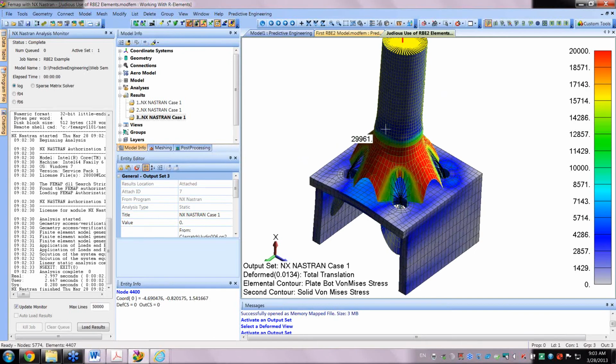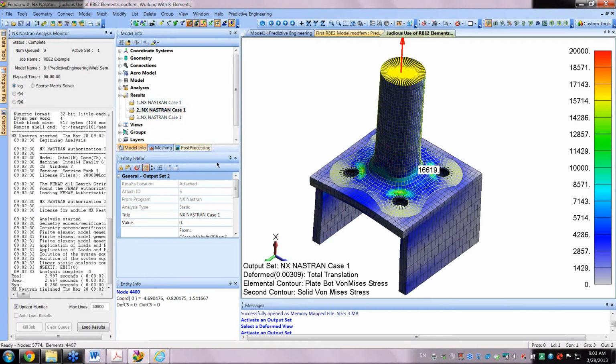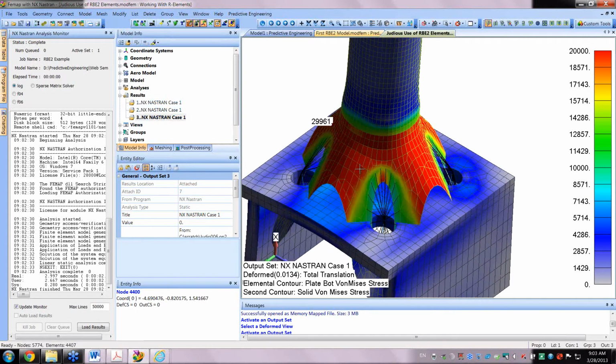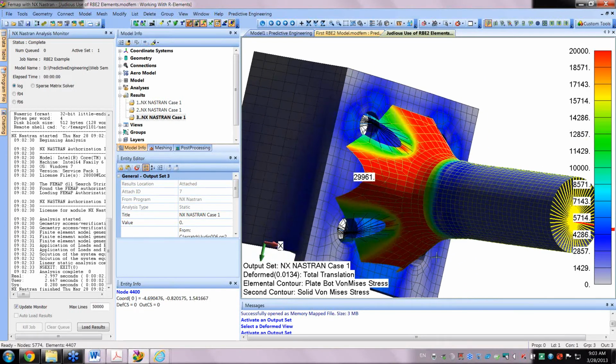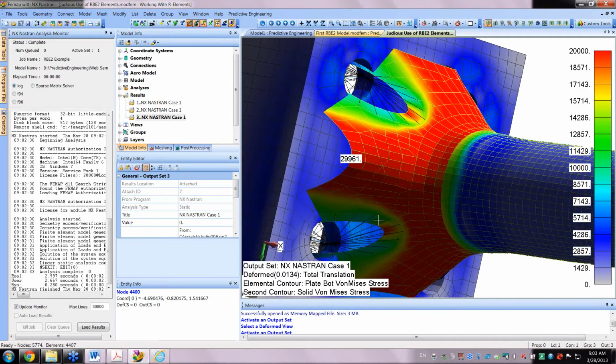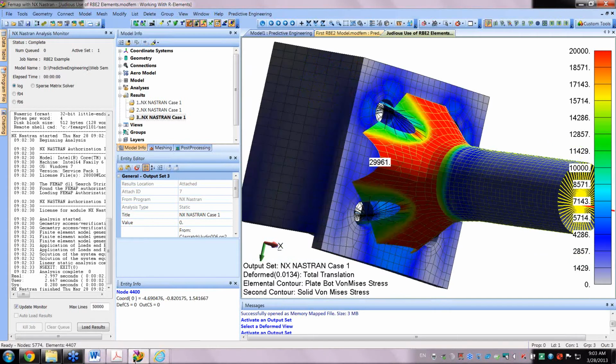I capped the legend at 20,000 just to make it. So I know there's some people out there, I'll leave unnamed, that would say, oh no, bolt heads, you've got to use an RBE3. Don't want to transfer too much stiffness. And I'm going, you sure about that? This example shows that they're useful, but you want to understand the physics of what you're doing. So not quite so good.